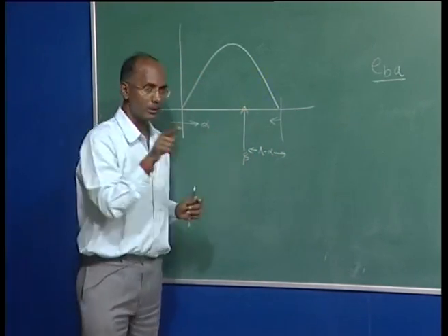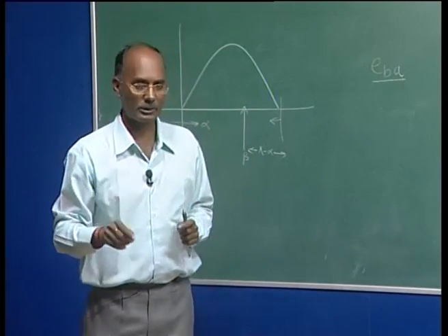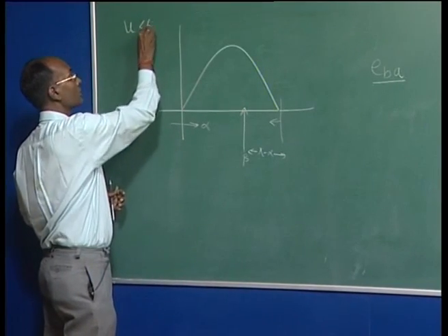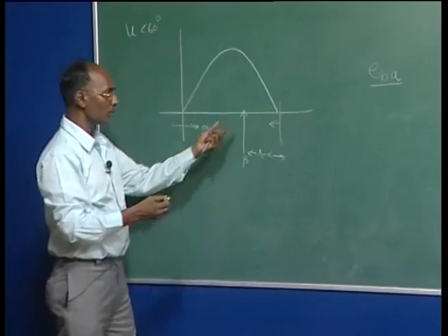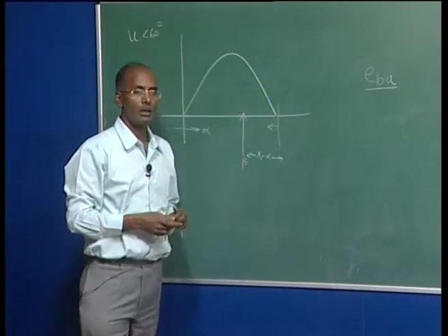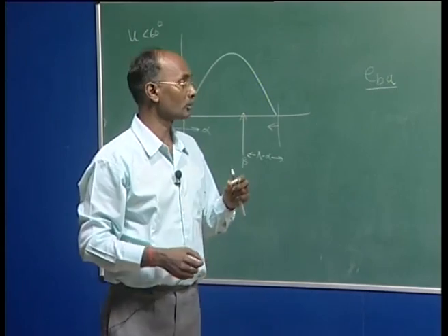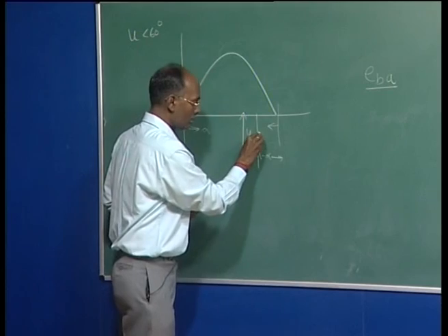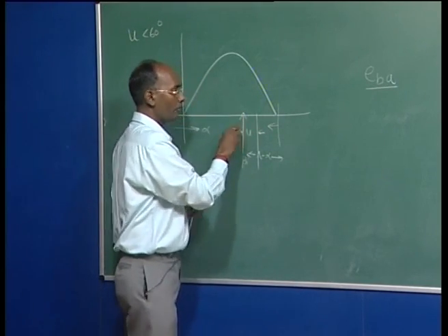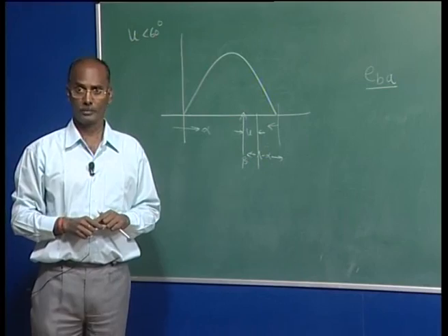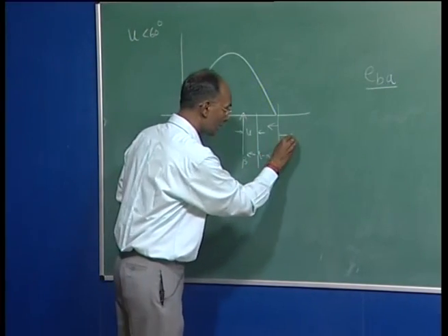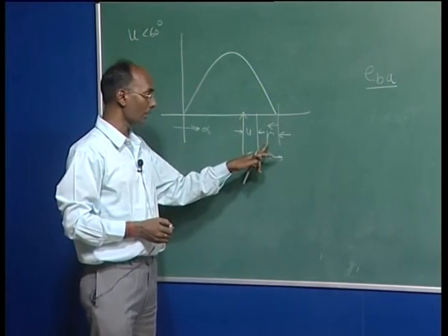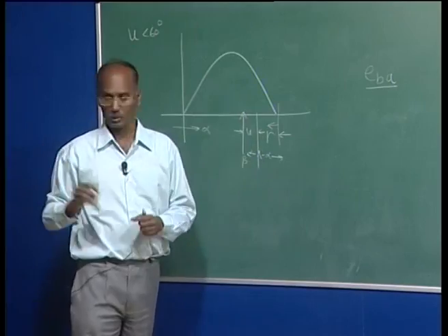Now, we are discussing the 2-3 valve conduction, which means there is some overlap angle u, and we are taking u less than 60 degrees. If you give the pulse to valve 3, the valve will conduct, but there is a commutation between 1 and 3, and it will go up to u degrees. Here it is u degrees, where 1 and 3 will be conducting. Now, this will be off, and this period is the gamma period, called the extension angle. So, gamma is nothing but beta minus u, which I wrote.